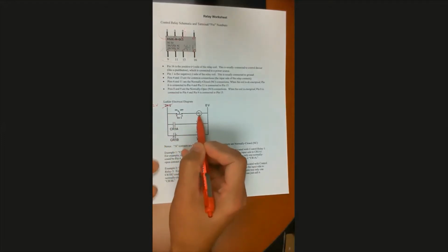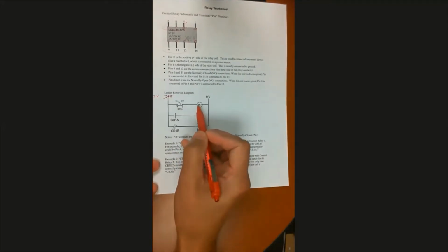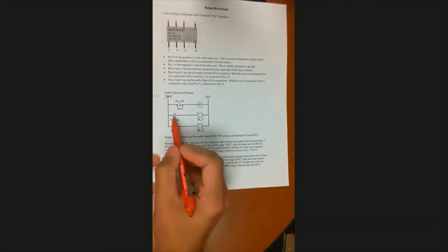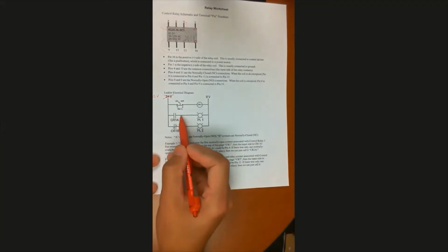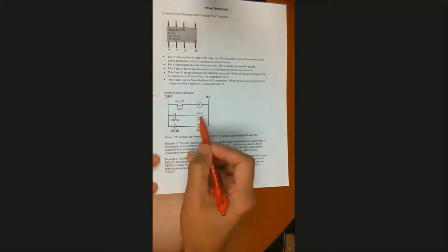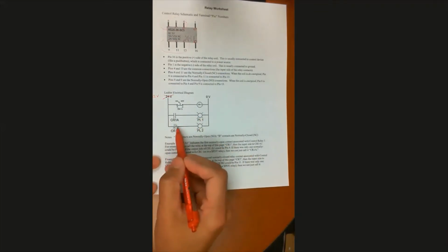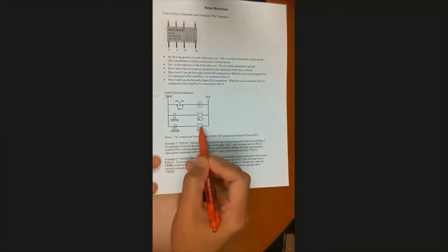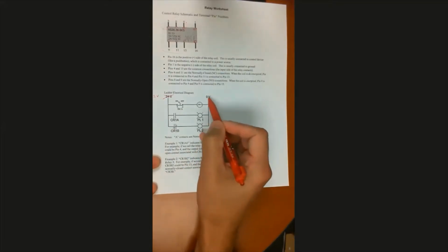So CR1, that's the coil of control relay 1, is de-energized. And when it's de-energized, then all the normally open contacts are open and all the normally closed contacts are closed. So they're in their as drawn state. So this remains open and this remains closed. And if this is open, there's no connection through here. And if there's no connection or continuity through here, current can't get through here, and PL1 remains de-energized. Meanwhile, this normally closed connection does have continuity through it, and PL2, therefore, is energized. And then make sure you get your wires back to 0 volts or ground. Okay. All right, so that was when it's off.